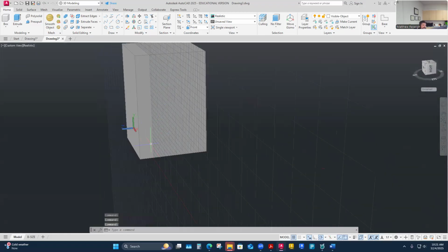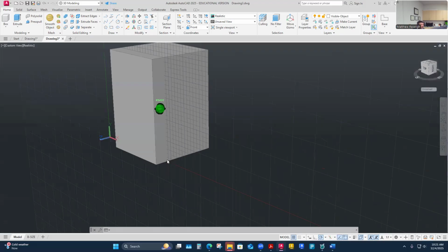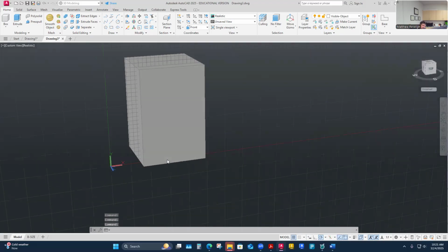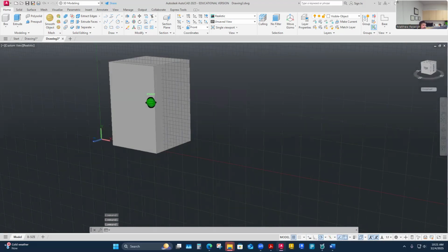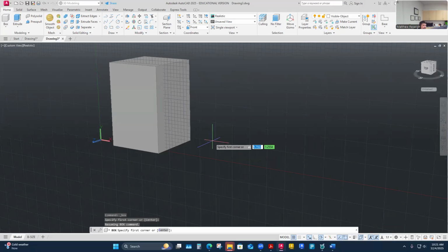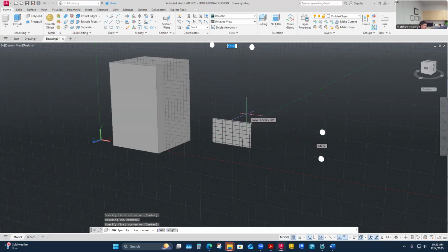The reason why this is there is because that's where I placed it. When I drew it there, it was kind of in positive and negative Z value in a little ways. It's kind of confusing, I know. But if I draw the box command now, what I'm looking at is still two coordinate points, but it's going to be on this grid here. So if I draw the same size, see, it's going to go this other direction. It's going to be like 4, tab 4.